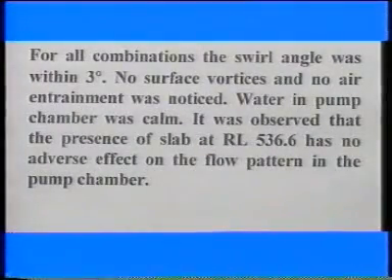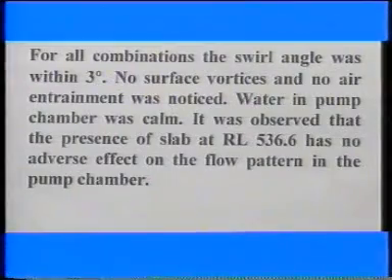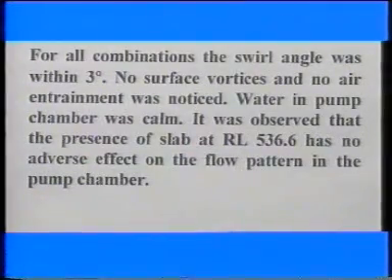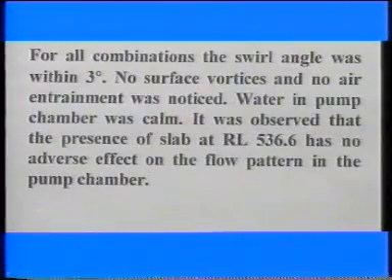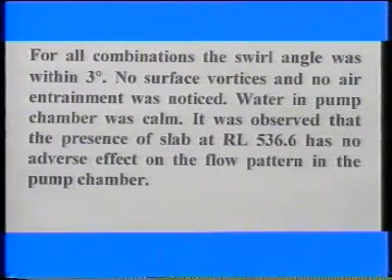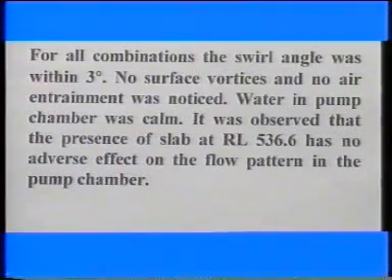For all combinations, the swirl angle was within 3 degrees. No surface vortices and no air entrainment was noticed. Water in pump chamber was calm. It was observed that the presence of the slab at RL 536.6 has no adverse effect on the flow pattern in the pump chamber.